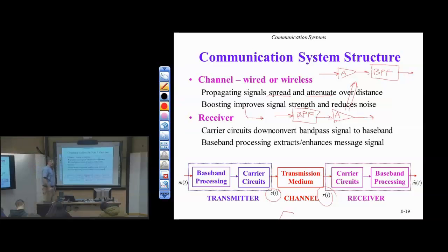Now, what happens in cellular systems for base stations? In today's deployments there are relays, and they have different names. The idea of the relay is to get a better signal to you, or in some cases, get a signal to you. Think about a base station mounted on top of a building in an urban setting, and there are some places around the base station that it can't get a good signal to. So what we do in deployments is put what are called pico cells, which are going to be on lampposts and so forth, to then serve as where you get your signal.